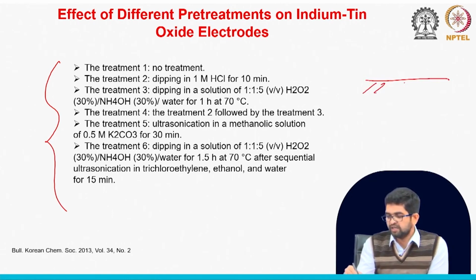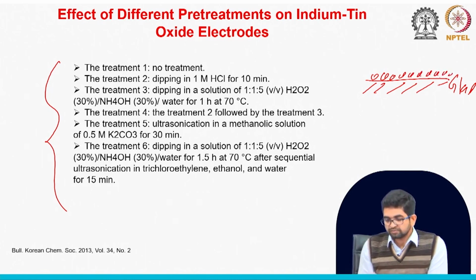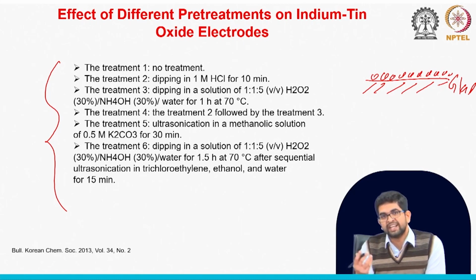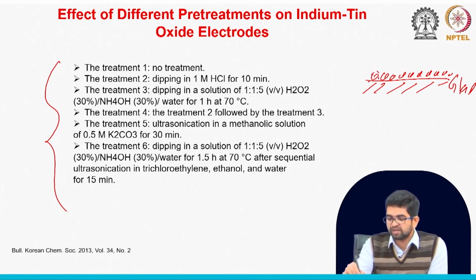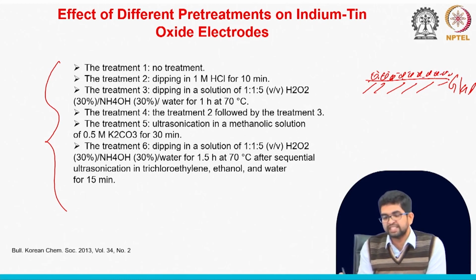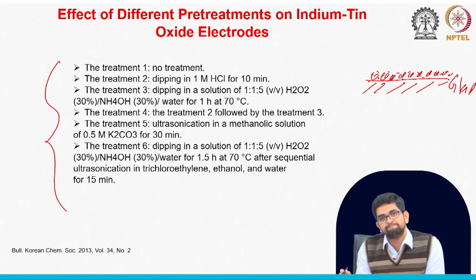ITO means glass surface with indium tin oxide coated nanoparticles, right? As I told you, when you receive this kind of electrode from any company and any industry, they have lots of contaminations and they cover the active site of the sensor surface, so we have to remove them.